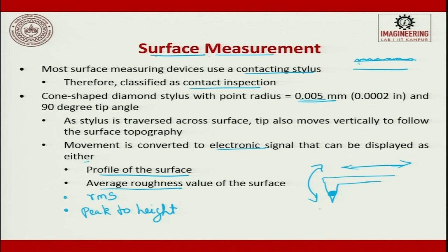These are some of the parameters which are used to measure the surface. Okay. So, once we have a lot of data, we try to figure out the average roughness top and bottom, and we try to make the uniform distribution of top and bottom. So, there is a shift in the central line. How much the shift is will be reported as average roughness. An interesting thing we should understand: whatever roughness value RA you get, you can have two different signatures, but they can give you the same data. So, people always argue that measuring roughness is not the only right parameter for the surface. They look for other combinations.